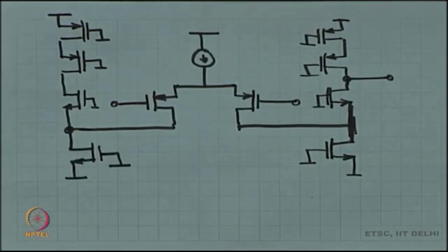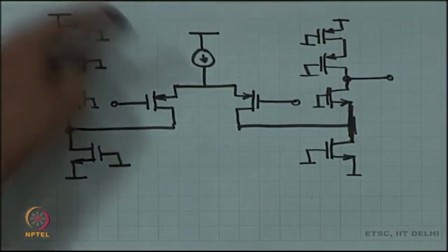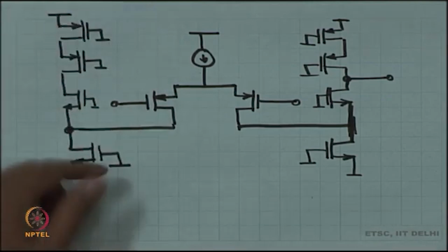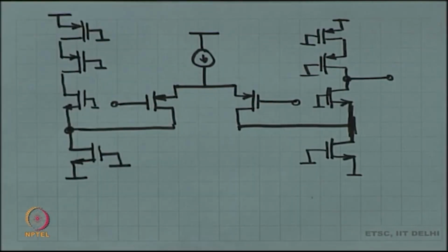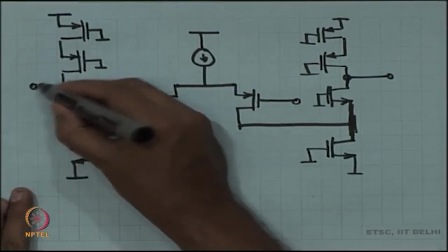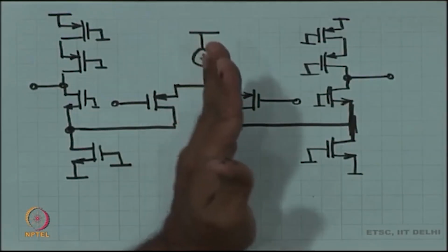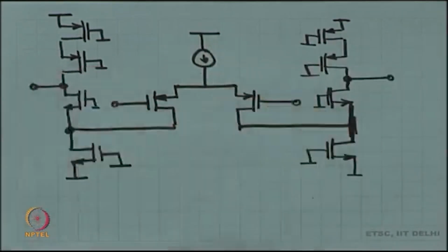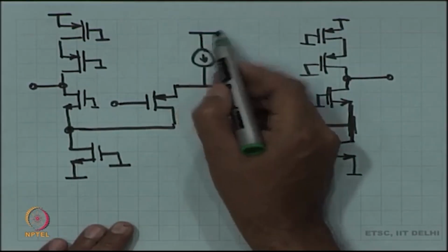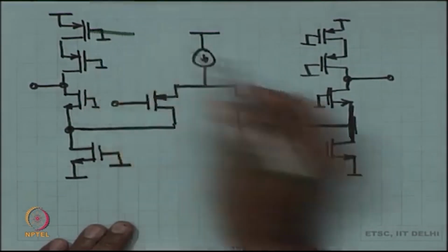Okay. So, the first thing you should notice is that my stack size has reduced. I have now got a stack of only 4 transistors. This is not the complete thing, this is still the small signal incremental picture. I have converted the differential half circuit into a full circuit. All right. Next we have to do the bias, the DC operating point.